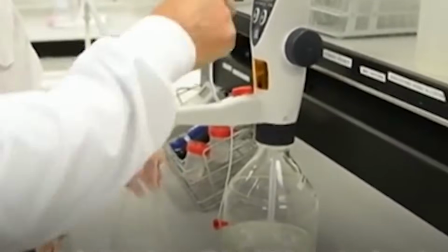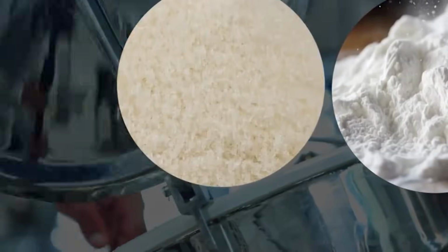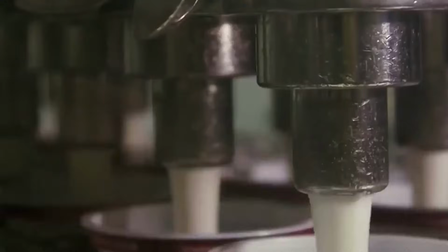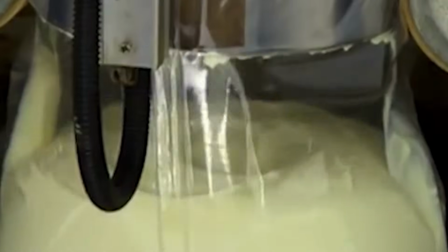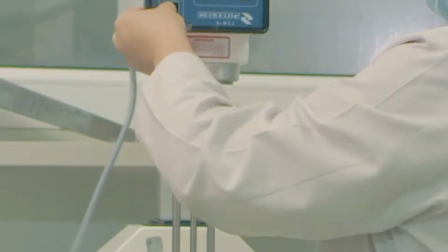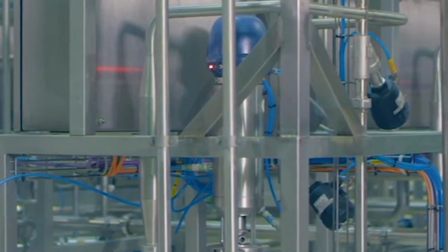design. For stick products or novelty bars, the yogurt is extruded into polycarbonate molds mounted on a carousel or linear track. The molds pass through a -30 C brine bath or air blast freezer for rapid hardening. Once the product reaches a core temperature of -18 degrees, sticks are inserted using servo-controlled plungers. The molded products are then released from the molds using brief exposure to warm water spray or ultrasonic demolding mechanisms.